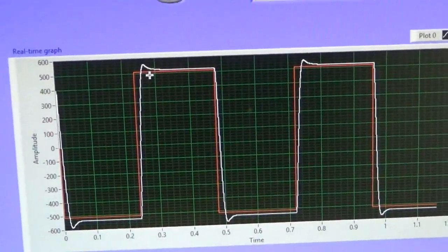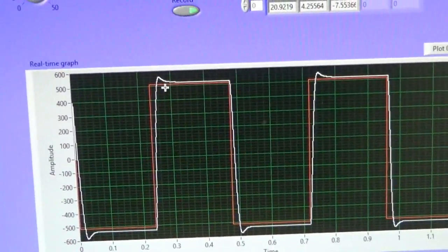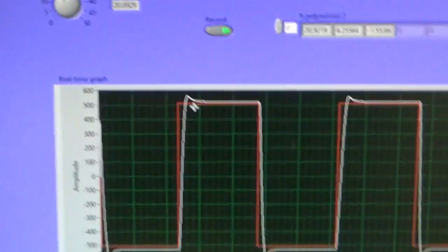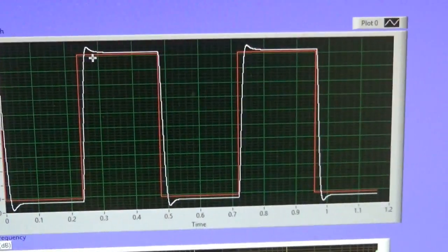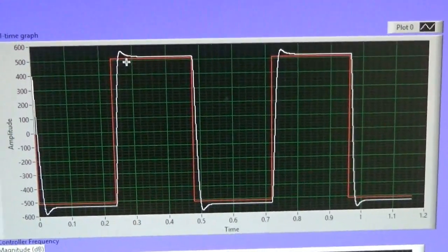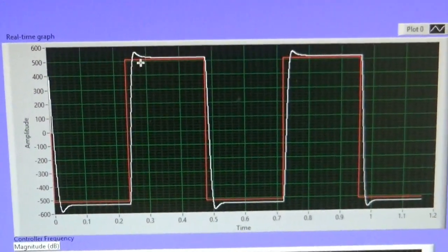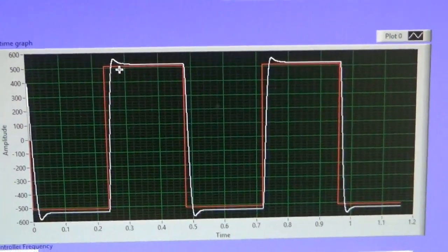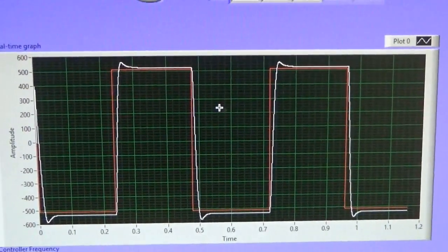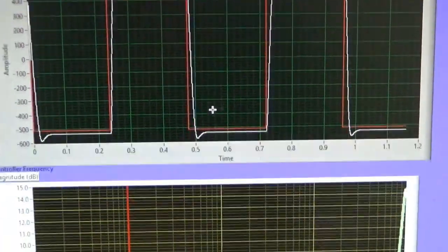It's not an electrical integrator, it's just a natural integrator because we're measuring position. At least we're measuring position here at this point. We never measured position when we did the identification, because identification is very hard to do when there's an integrator in the loop. So we measured just from velocity and then put an extra integrator in artificially.